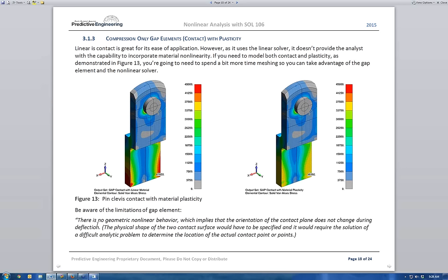Right. And I want to mention that this is an extremely powerful technique. It runs super fast, and it's what we use for Boeing's landing gear set on the 787, the Dreamliner. And it's just smoking fast. It's really the fastest sort of contact setup you can ever get using that sort of alignment. And Femap really facilitates this. It's really preferred, and it gives you great results. It just takes a little bit more upfront time modeling.